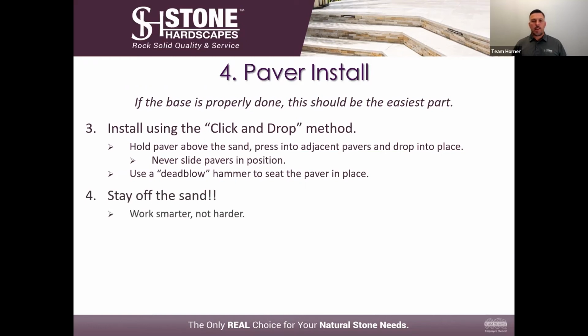This last part I cannot stress enough. Stay off the sand. Too many times I have been on job sites and I have trained crews who want to lay the sand down and then walk all over the sand. So the entire time, half of what you're doing is fixing the sand.